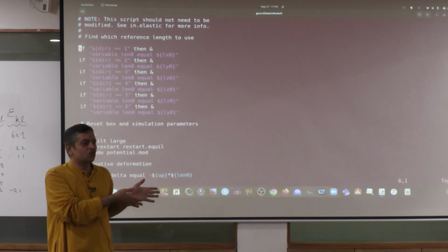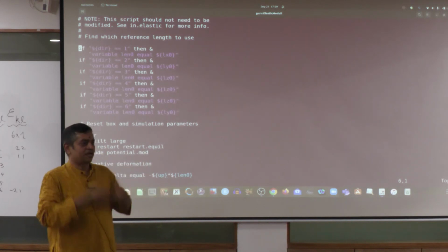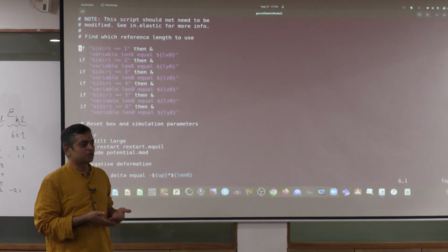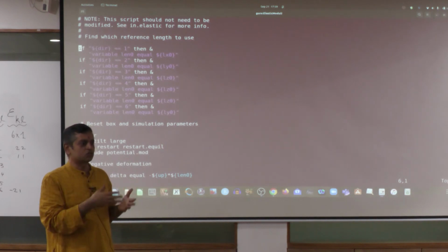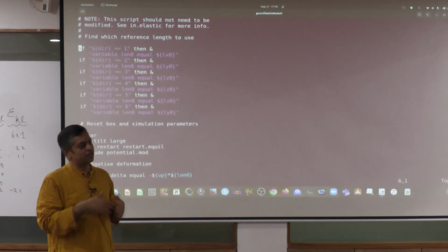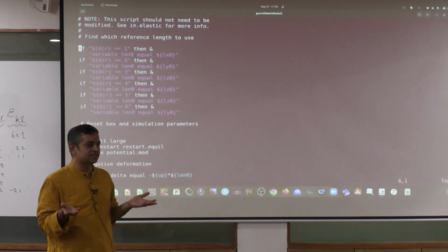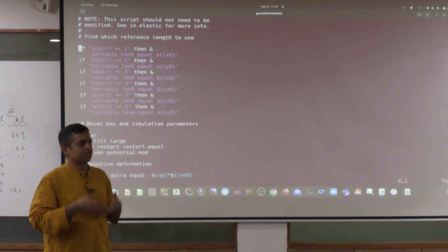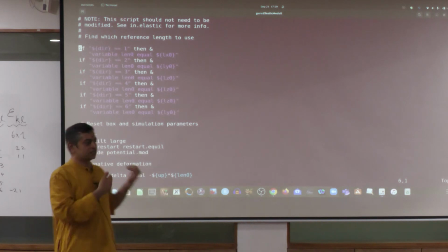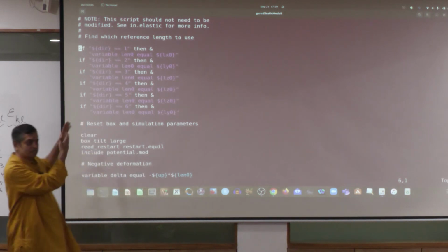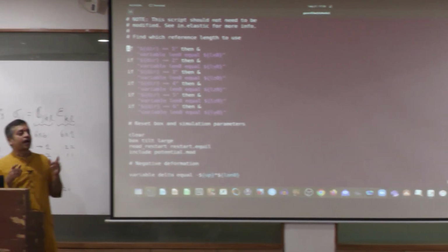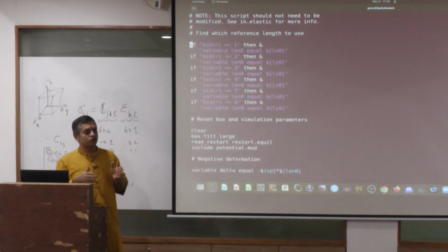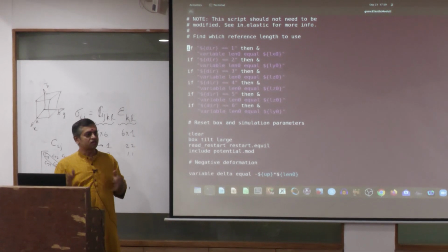So, the left hand side is known, displacement is known, I can calculate the corresponding moduli. But because it is cubic, for example C11, C22, C33, I will do all three of them, take an average and report that as C11, which is equal to C22, which is equal to C33. That is what is being done. That is why there is displacement, there is minimization, and we get the energy. And you can have this displacement both as positive and negative.